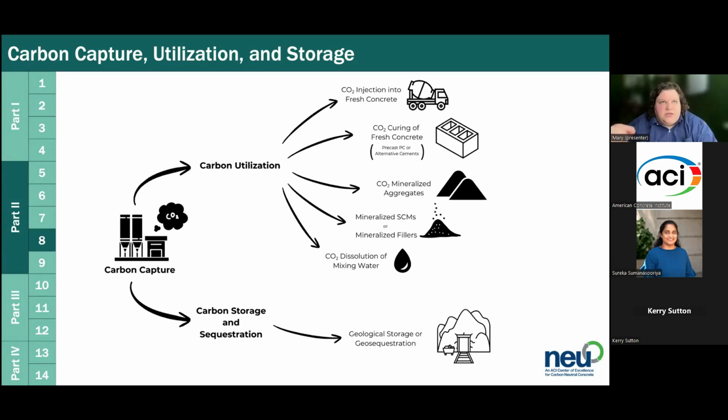It's just doing it really slowly and not a super ton. It depends on surface area. Some of these methods are trying to accelerate how much carbon can be pushed into the concrete. Sometimes they inject it into fresh concrete in the mixer. Sometimes they cure precast concrete in a carbon-rich environment, and you can make aggregate, SCMs, mineral fillers. You can even pump CO2 into water to dissolve some of the solids that come from the water you use from cleaning your truck.